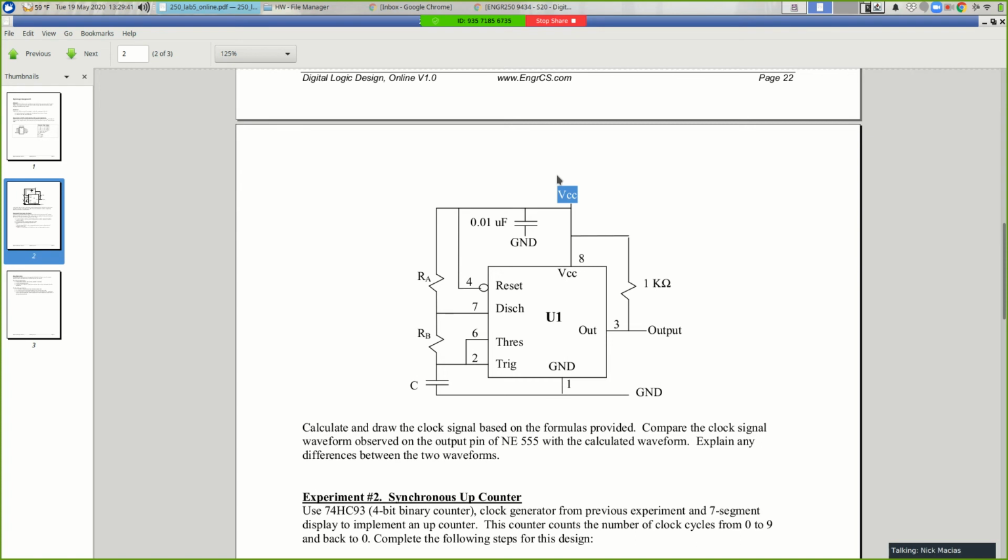Now this is not critical in this circuit, but in 270, again, maybe not on the simulation, but in 270 when you're doing things like driving motors, these become really, really important. Because in a theoretical sense, this is always 5 volts. In an actual laboratory, this will bounce all over the place. It'll go down to 4.5 volts, maybe 4.2 volts, maybe up to 5.5 volts, right? And that can really confuse circuitry, especially if this is a microprocessor.